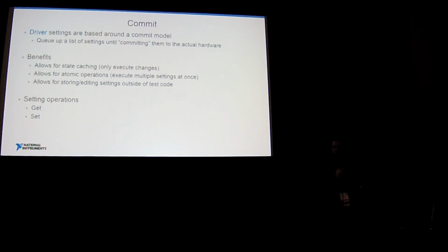And that list of settings could come from your block diagram, but probably better it comes from a file or a database. It makes a really easy system to start pulling those settings that are important for your test out. And what that lets us do is write one test, change the settings outside of that test, and not have to keep churning code or having code reviews or lengthy release processes, right? So this is a pretty powerful concept.